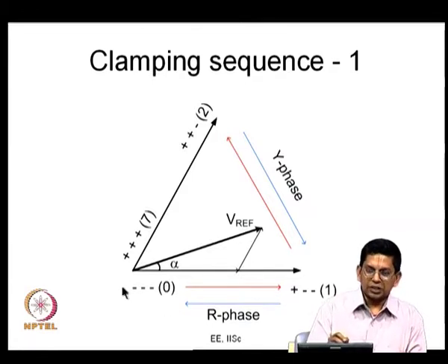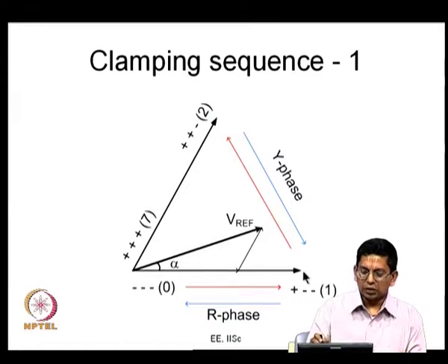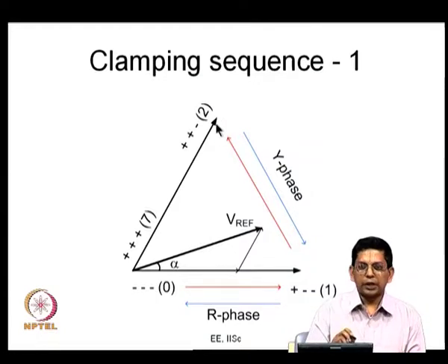You apply this for Tz seconds, then move here and stay here and apply for T1 seconds, and then after that you switch the Y phase and go here and apply this for T2 seconds, and the result is the same.